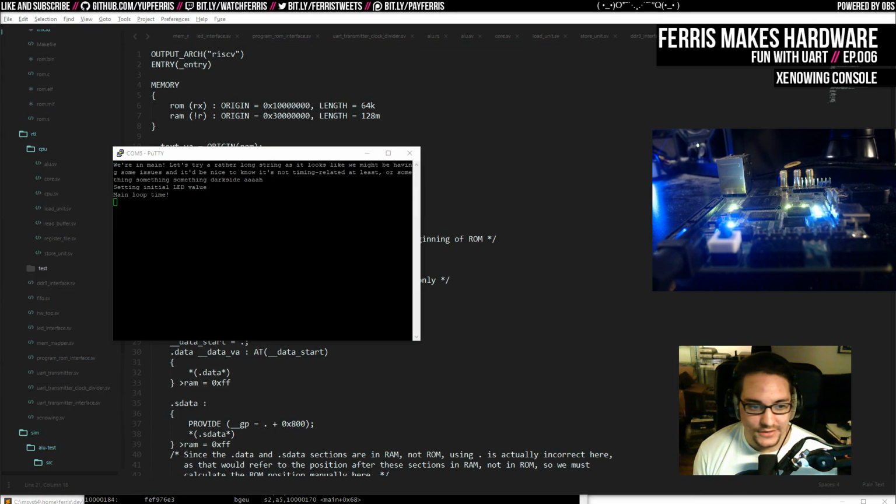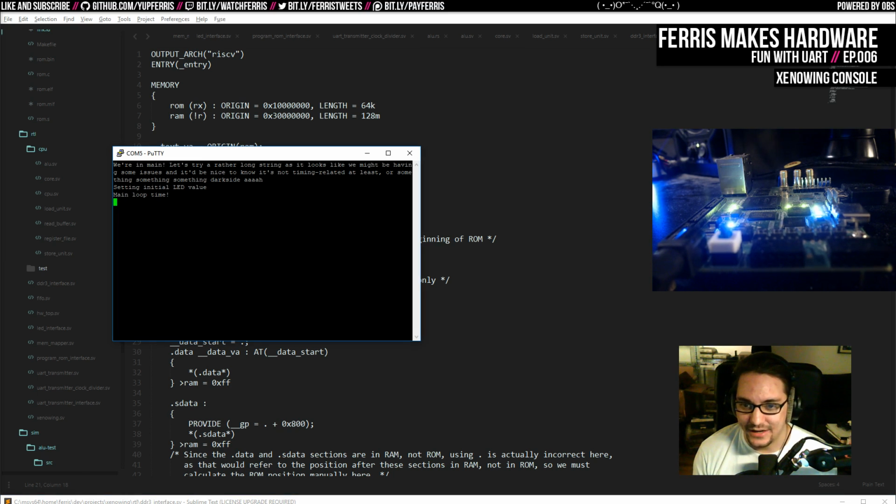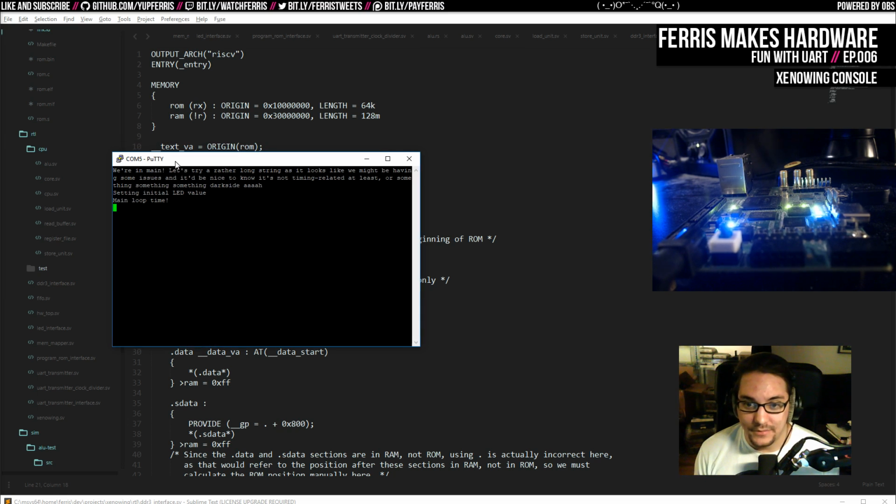But I didn't want to do too much more of that today, at least not tracking down more of these CPU bugs, because it really is boring. I'll put the thing on the FPGA and the LEDs won't light up, and then it's like, okay, what happened? What did I get on the UART? Did I get half a string? Did I get something else? And then it's just reducing until I can figure out where the problem is, and then finding where things went wrong in the timing diagrams.